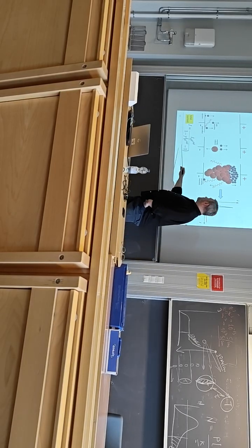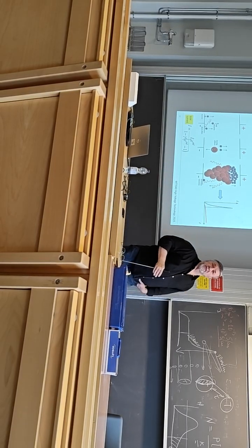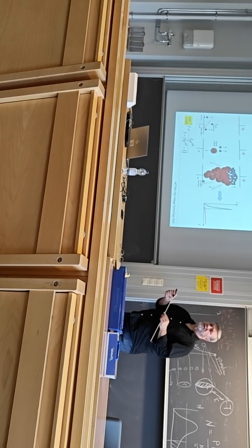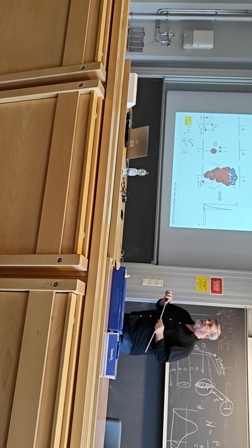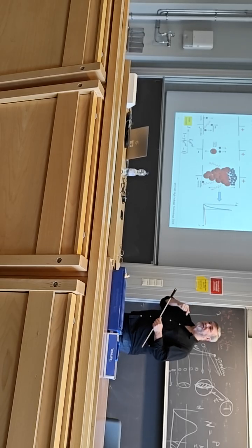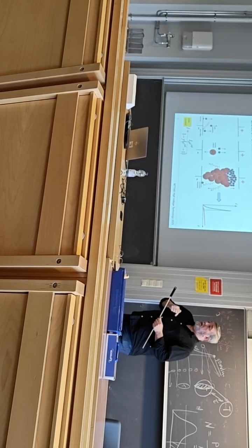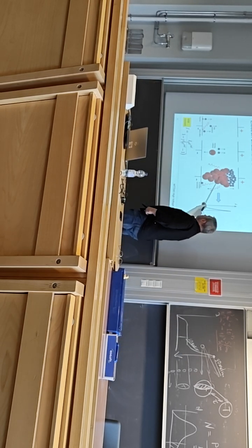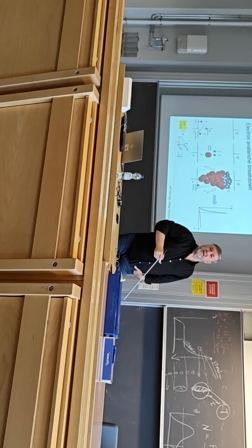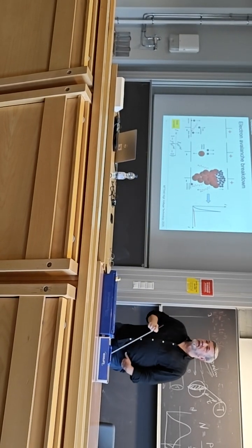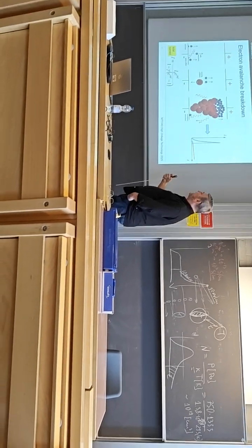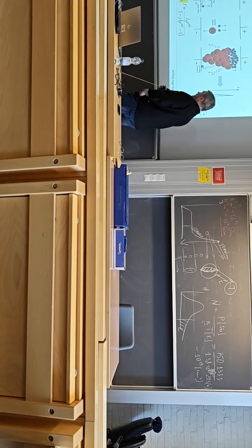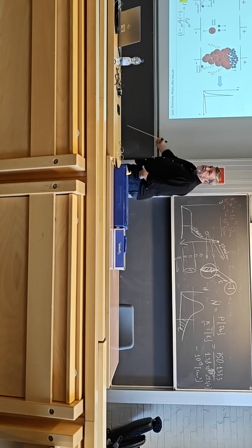And usually for air and, say, copper, this type of combination, gamma at atmospheric pressure is about 10 to the minus 4, 10 to the minus 3, meaning that one electron is released statistically due to the impact of roughly 1,000 or 10,000 ions, something like that. One of them has enough energy to release a secondary. That's again a statistical parameter. It's called the secondary ionization coefficient.